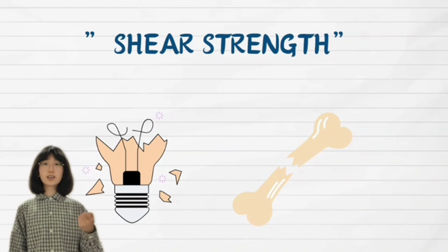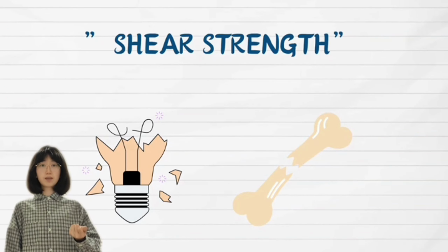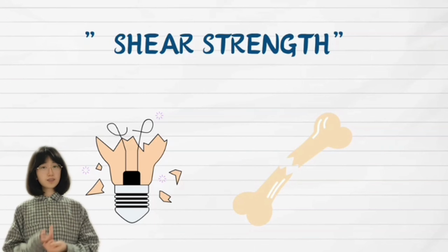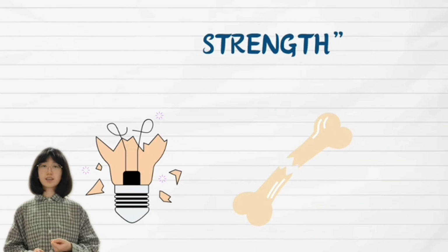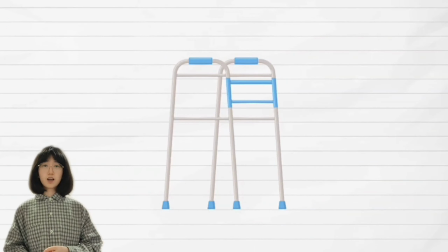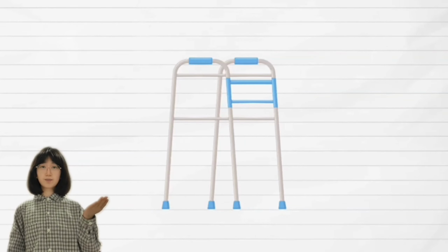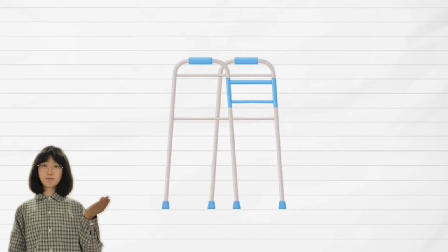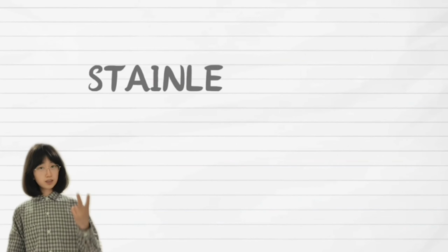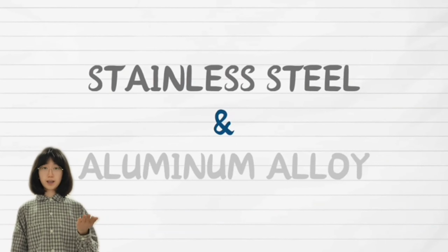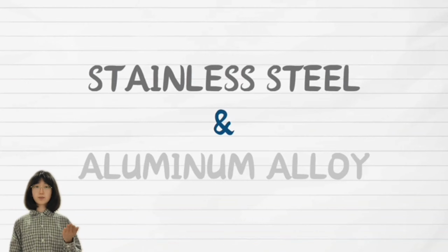It's the maximum strength the material can withstand under shear forces. Sometimes the force applied can cause torsion in the handrails of the working frame, leading to rotational deformation. This is another critical factor to consider when selecting materials. Now, our next step is to calculate the maximum load-bearing capacity of the handrails on the working frame under different strength conditions. We have considered two materials, stainless steel and aluminum alloy, and derived relevant data based on their respective moduli.